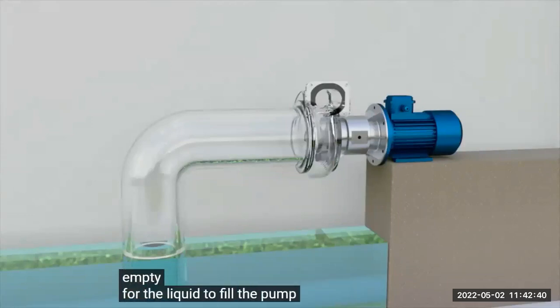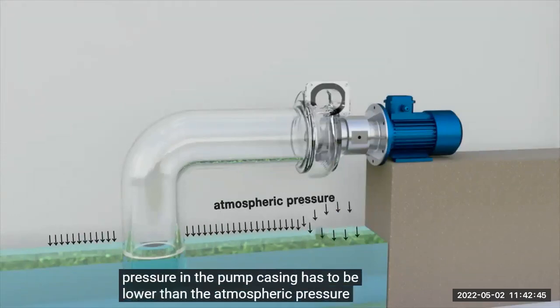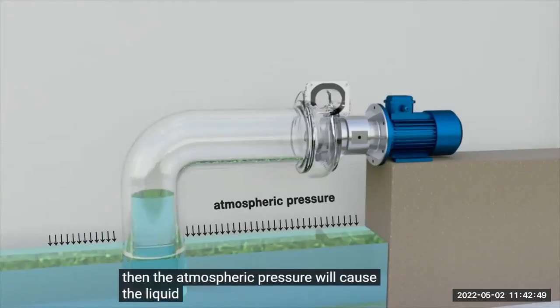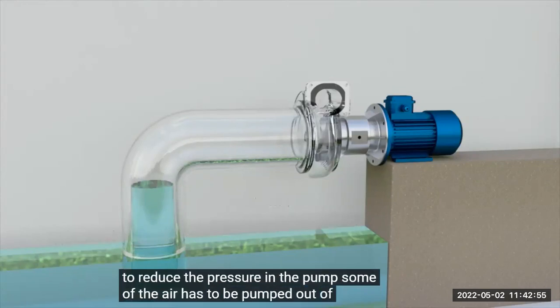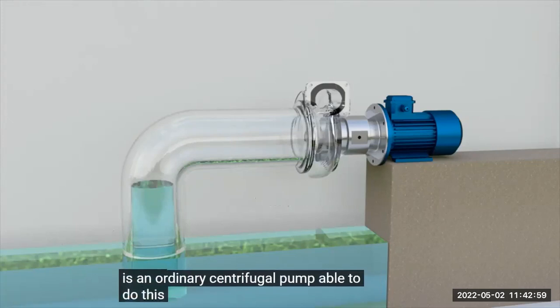For the liquid to fill the pump, the pressure in the pump casing has to be lower than the atmospheric pressure. Then, the atmospheric pressure will cause the liquid to fill the casing. To reduce the pressure in the pump, some of the air has to be pumped out of the casing. Is an ordinary centrifugal pump able to do this?